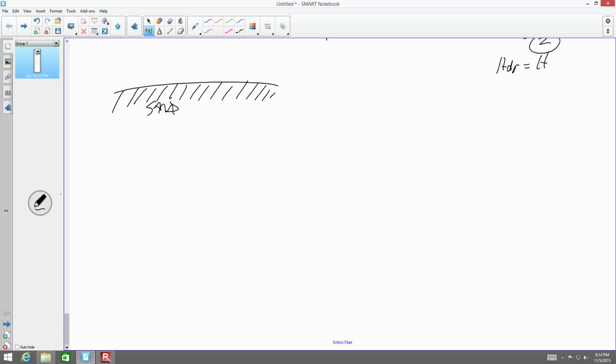An undisturbed sample. It'll take 4 times as long for the consolidation, 4 times as long for consolidation to occur. An undisturbed soil sample has a specific gravity of 2.7. The moisture content equals 10.5%. The void ratio is 0.63. The degree of saturation is most nearly.